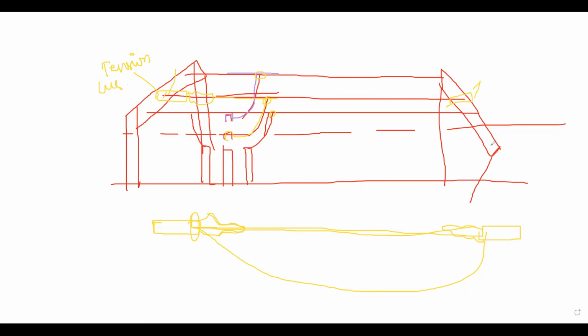And now this is the bus. Now this conductor should extend from this bus to the next bus. I am having a next bus here. I cannot string this conductor for 50 kilometers, or 30 meters, 100 meters. There should be some limitation for the conductor. For 220 kV, the limitation is 34 meters.